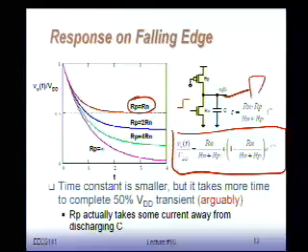If I connect this to a normal inverter, I might have to say, well, gee, for this thing to flip, I have to look at this 50% point between 0 and VDD. However, if I would connect this to another pseudo-NMOS inverter, I think actually the more plausible argument is going to be the 50% point between VOH and VOL. Makes a big difference. Because if I look at the 50% point between VOH and VOL, I indeed get that answer. It says, hey, I'm going to be faster.